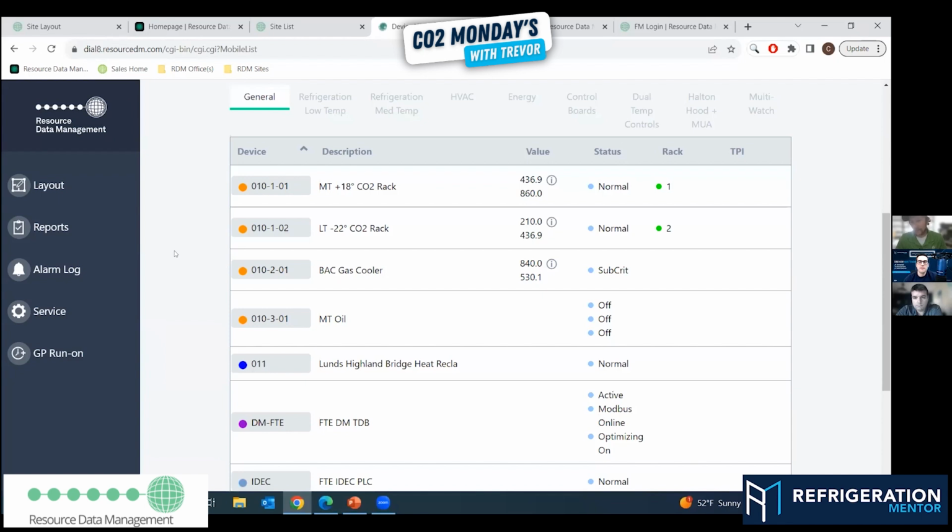Guys, I've turned cases all the way up to 15 to 18 degrees on the set point on the controller that actually equaled 8 degrees. You have to pay attention to stuff like that too. Just because a controller says that's what it is doesn't mean that's what it is. You have to check this stuff. And there's a lot more checking with all these controls and all these sensors and temperature probes.